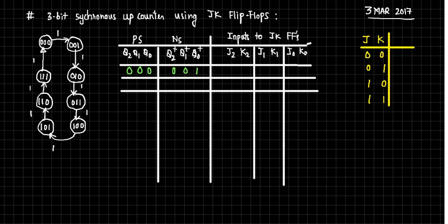What happens when it is 0, 0? You tell me. No change, right? So no change. Here it will always reset the value, it will set the value, and here it will toggle, the complement. Now this is all Q plus, no? I mean the next state. Not the Q bar, okay, Q plus, the first output of the JK flip flop.